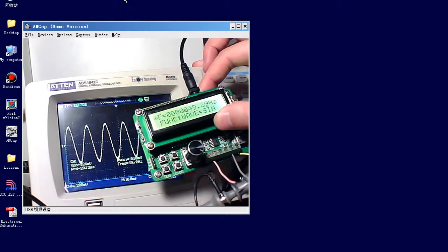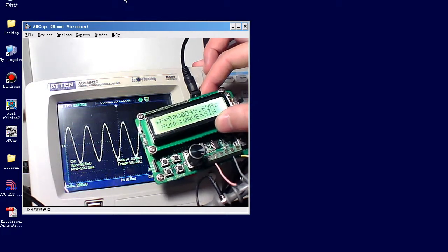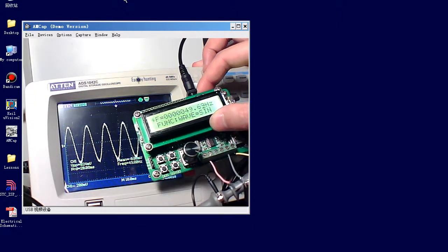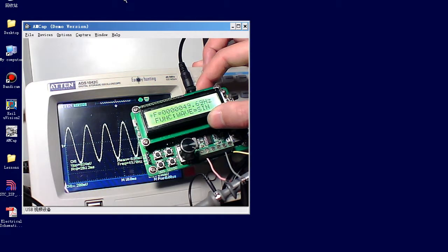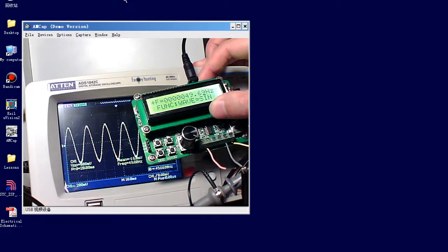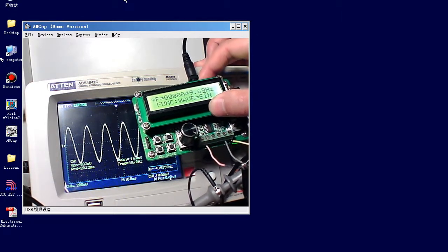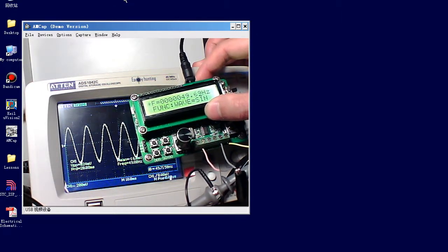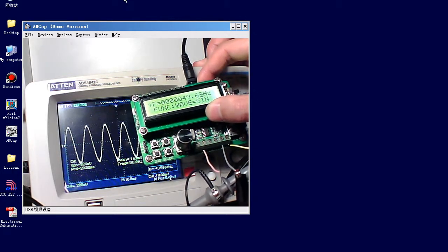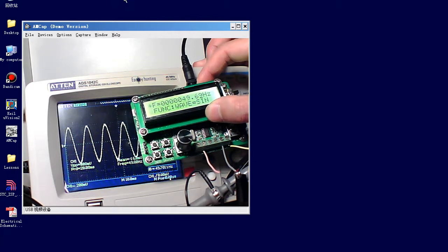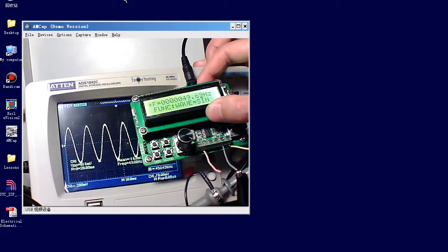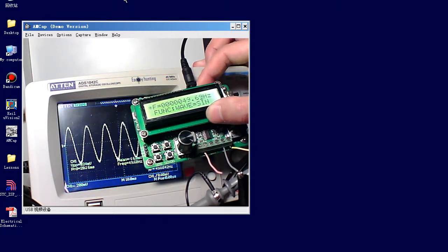The question is how can I achieve the control purpose to control the frequency by using those 4 pins. Basically what I'm thinking is I will use our experiment board to try to detect the analog input, and then I'm going to use the analog to digital converter on the experiment board to convert the analog signal into a digital signal, and then we will use the microcontroller to